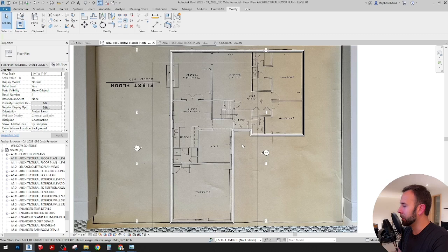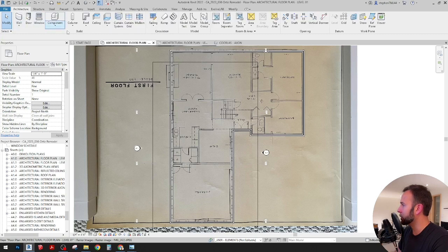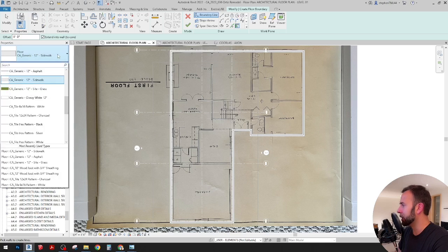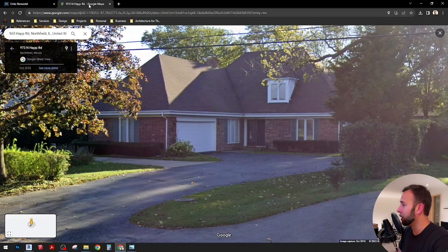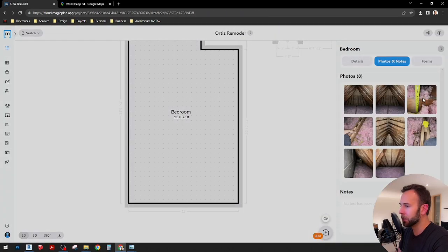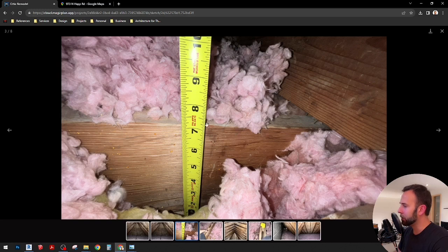Now, to model in a floor plate, go to Architecture, Floor, and I've got some models that basically just have the joists in place. I do know that the majority of the joists, at least based on my survey, are under 12 inches, so they're undersized. I measured the actual joist that was in the garage, measuring that beam that was going across, and these were suspended joists, which is a unique condition, but these look like they're 7 1/4, so 2x8s.